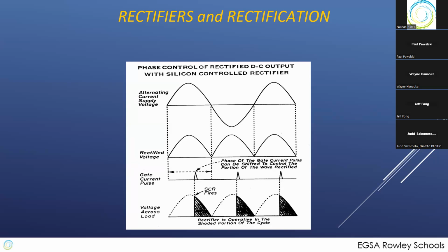And the reason this is better in risky environments is that thyristors and SCRs are a lot bigger. They have a lot bigger layers in them on their equipment than the really, really tiny transistor traces that are in a modern microcontroller. So these big, bulky, old systems can handle a lot bigger EM pulse before failing.